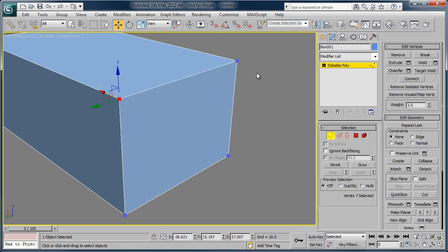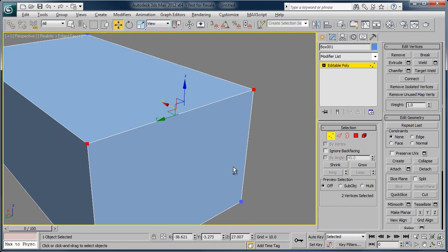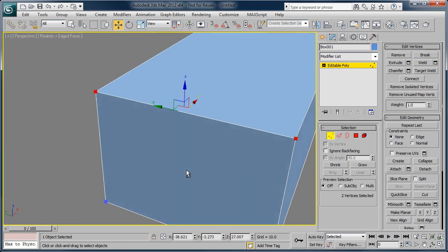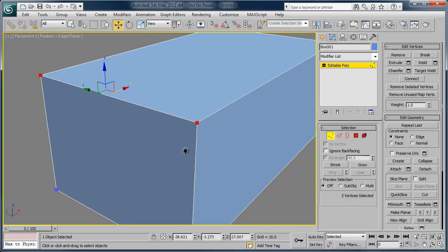And so one quick thing you can do is grab a selection of your sub-objects, for example these vertices, press Z to zoom in and frame those vertices, and now as you truck the camera around, you'll see that the camera orbits around it. And so you're going to want to check that and make sure that you have that set on your personal viewport as well.